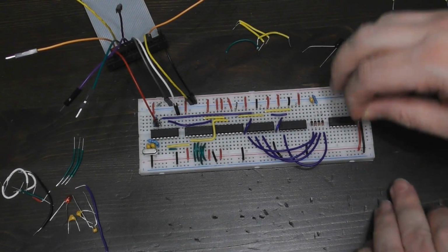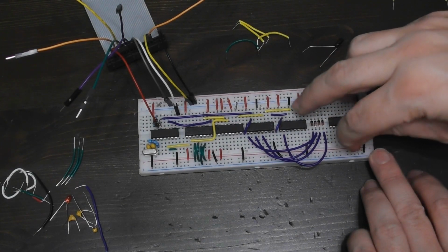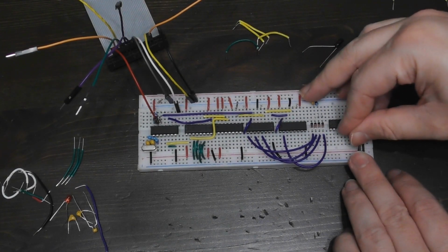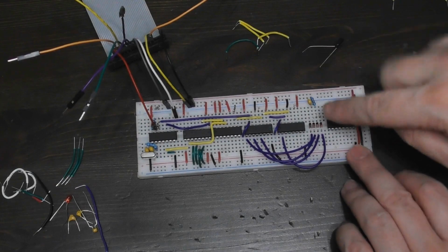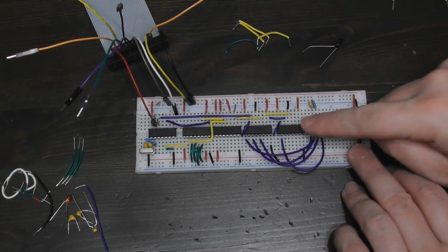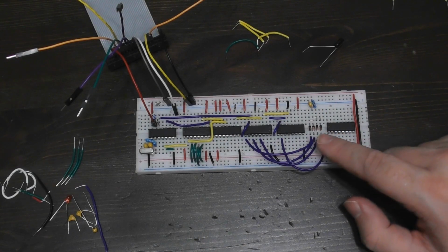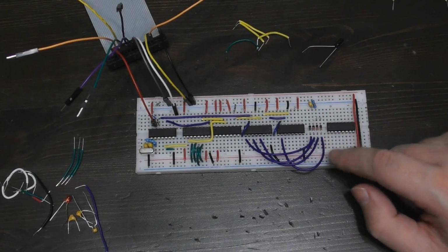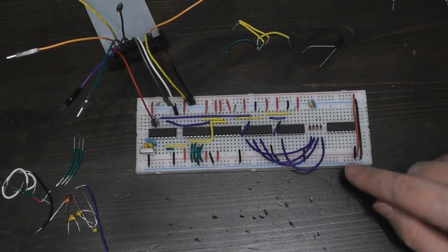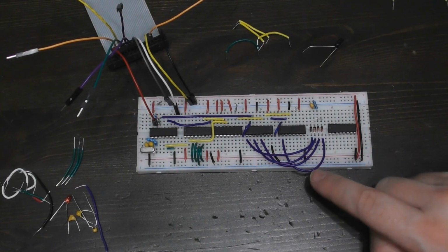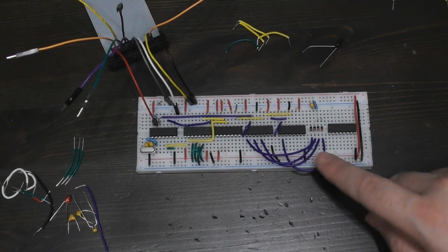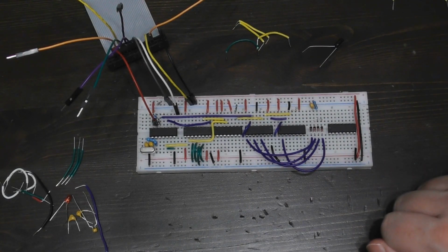So I'm going to put this counter in, and initially it's going to count 6 of my reconstructed clock pulses, because that should take us from the point at which the address mark detector gets triggered to the very end of the address mark. Remember that the address mark trigger is based on a point about 6 bits through the byte rather than 8 bits. So there are a few more bits to pull, and I think 6 clock ticks is what we need to wait, from my earlier calculations, to allow the shift registers to accept those extra bits. Then the shift registers should contain the full clock and ID of the address mark.